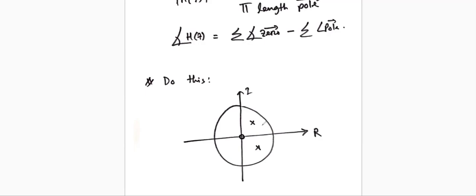Okay, so at this moment, this is the portion where we have covered the basic understanding of the z transform, as well as how to represent it in the z-plane, the pole locations and the zero locations, and how we can even interpret the z-plane representation with low pass filter and high pass filter, because you can plot the magnitude response from this plane representation.